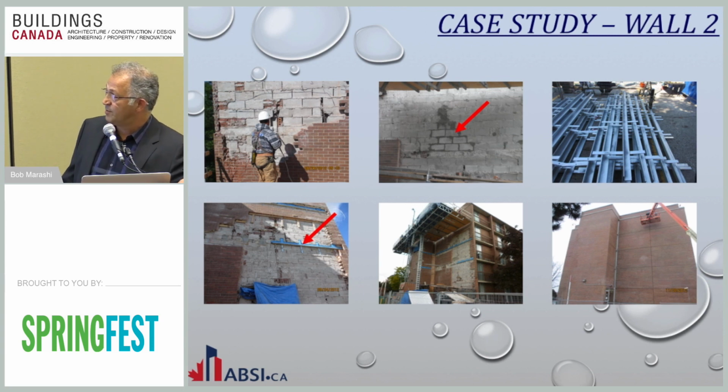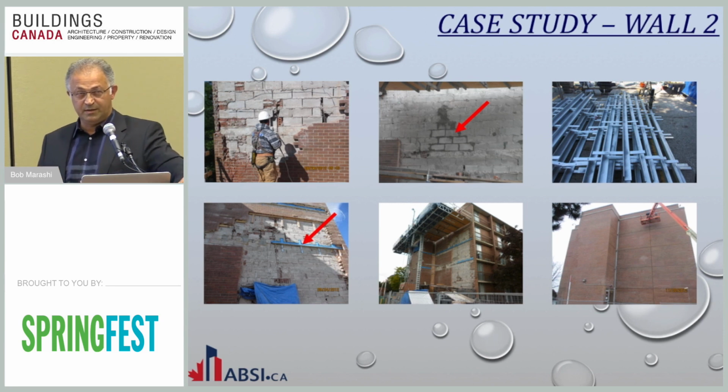So we introduced some shelf angles. The panels, the backup block walls, were not secure, so we put some stiffeners in there and put the wall back together as we went. And this building, I think, is being demolished or will be demolished by next year.